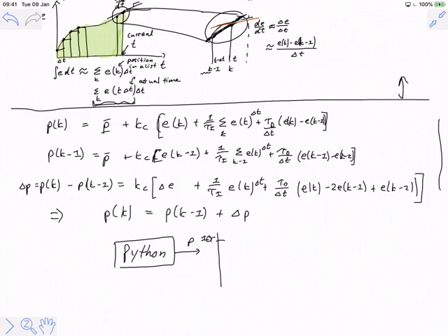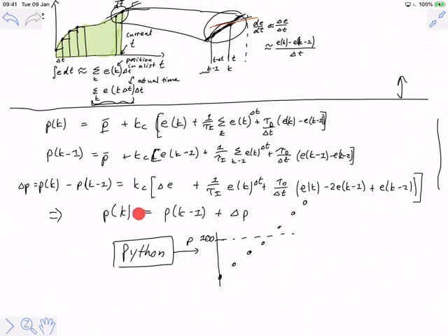Maybe it's 100. So I start at some value, and in successive calls to my controller function, I'm calculating higher and higher output values. At some point, if I were using a position form, I calculate higher and higher values. If I just do the calculations in Python, I will keep calculating exactly the same values. Why? Because the Python program doesn't know that the output has saturated.